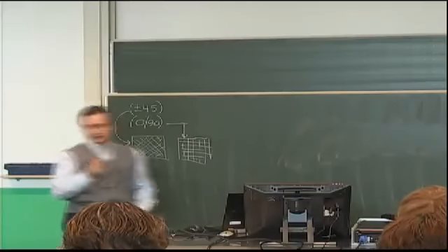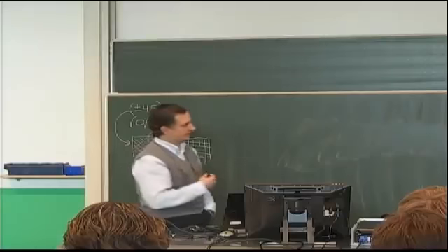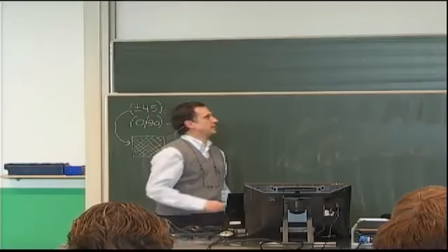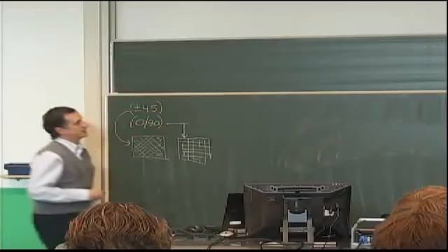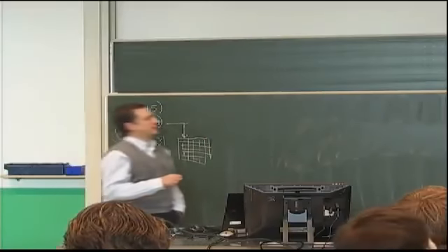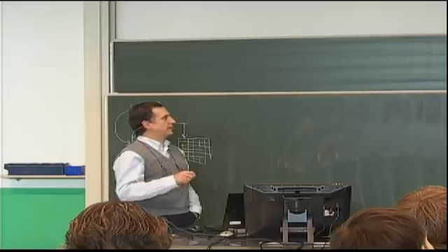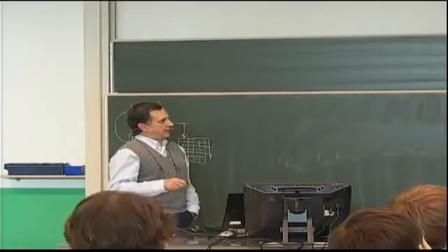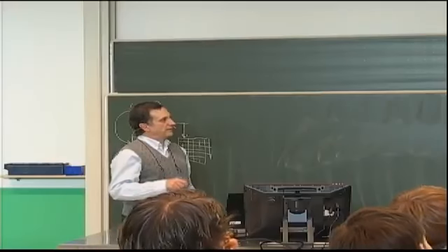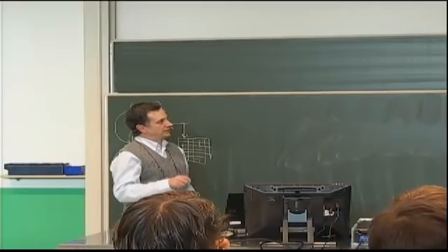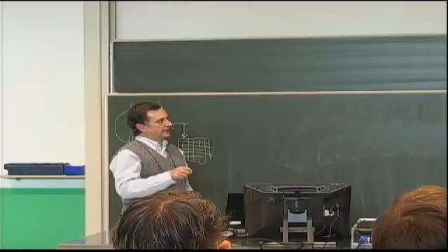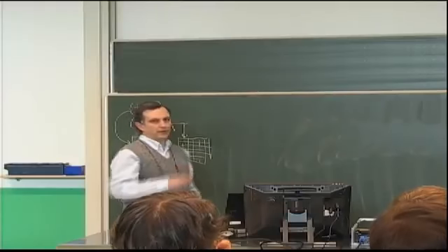Remember, there's a whole bunch of stresses. There's a sigma y and tau xy stress that we also have to double check and see what they look like. So this one is the shear stress, hopefully. Yeah, this is the shear stress, again divided by the far field stress. And it's plotted as a function of y over b. So we are going from left to right. And it's done at x over a equals 0.0075. So we are not exactly at the top edge, but very close to it.